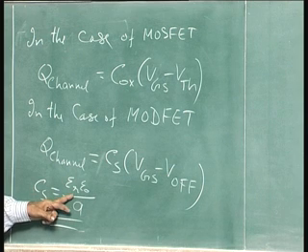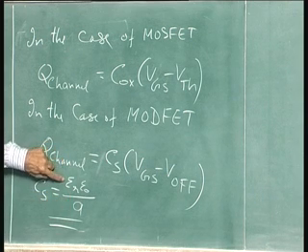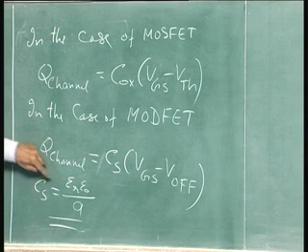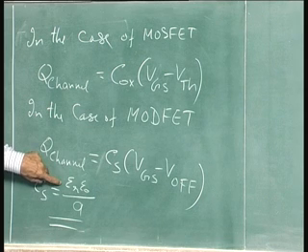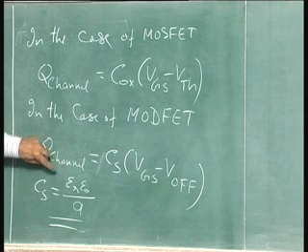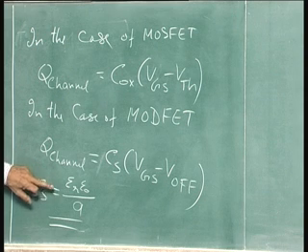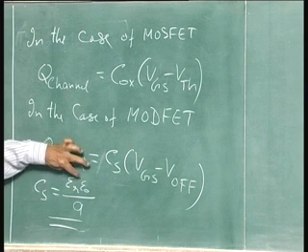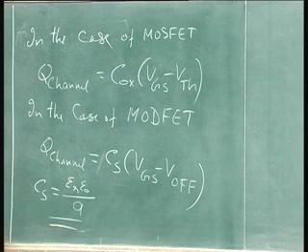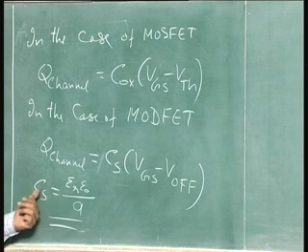In the case of MOSFET, this quantity is 4. In the case of GaAs, this quantity is almost 12.8 to 13, about 12.8. So, about 3 times more in the case of HEMT. This is about 3 times larger than that of the MOSFET C oxide. Epsilon 0 is the same thing, and A we are taking the same for comparing for the same situation. This will have CS which is about 3 times larger.